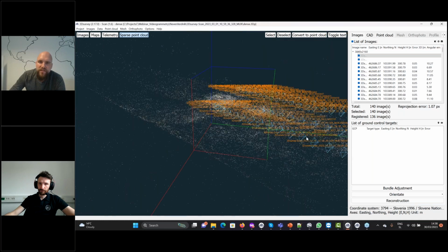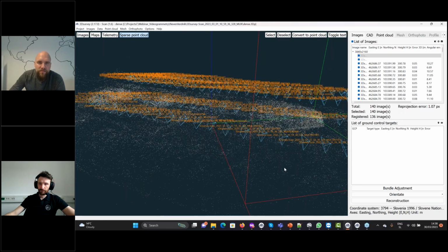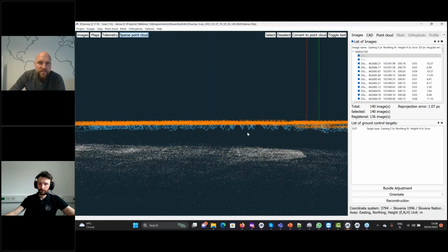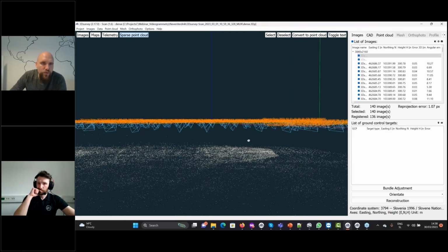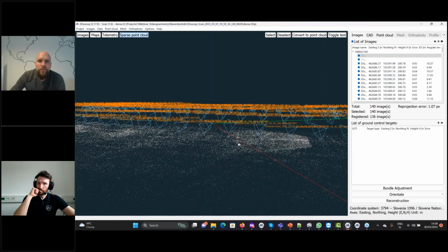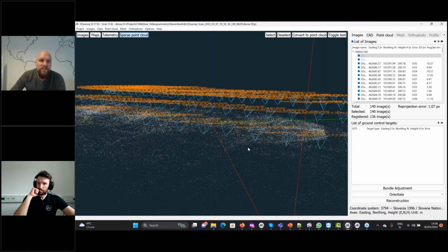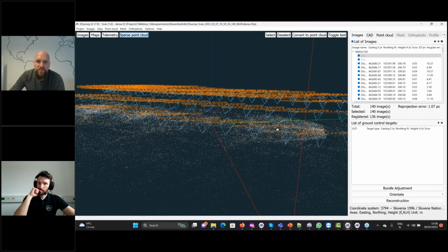So this one was actually mapped by one of our customers. So here we can see, in this example, the camera was facing slightly more forward than down. So I think we even get slightly better results when we rotate camera slightly more downward than forward, but not too much, of course.